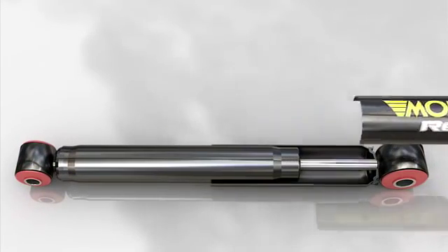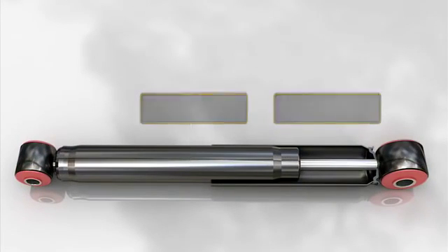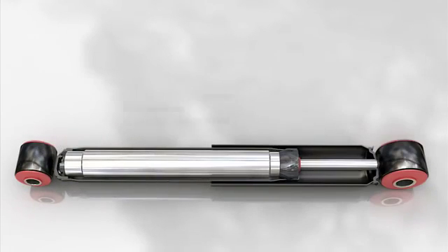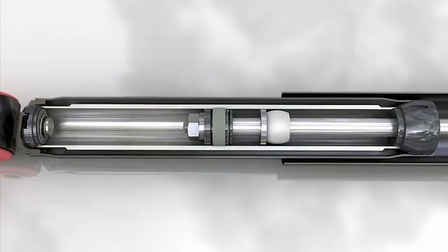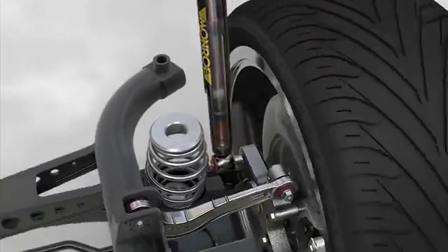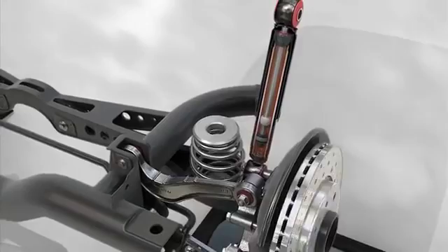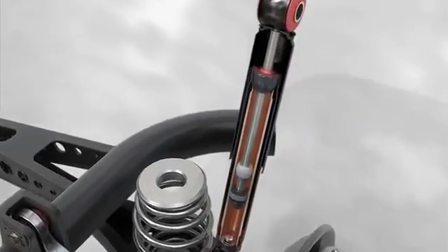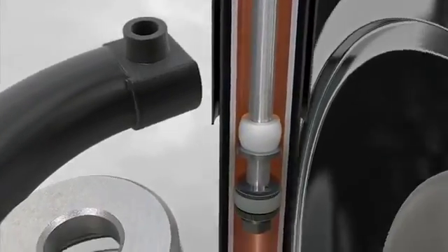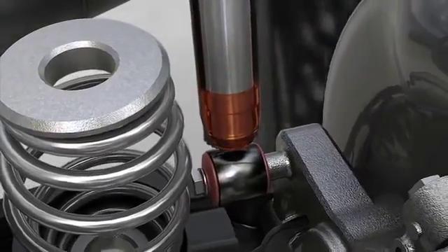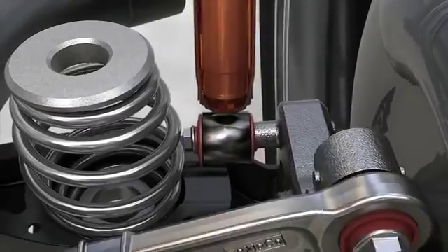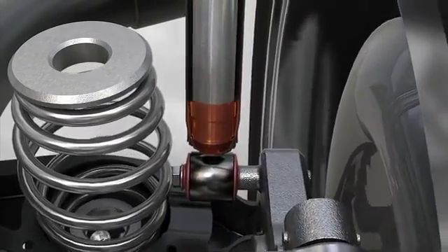Twin-tube shock absorbers, as the name suggests, have a body made of two concentric tubes. These tubes create the working chamber and the reserve chamber. For the shock absorber to perform its function properly, the working chamber must be full of oil at all times. Otherwise, the valves would be operating in air, causing them to malfunction. The reserve chamber will always be partially full of oil because its function is to ensure that the working chamber fills with oil, regardless of how compressed the shock absorber is.